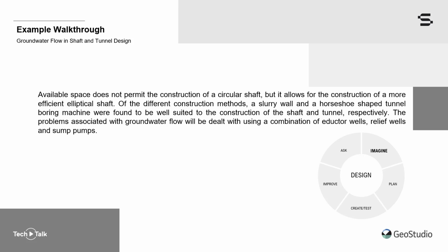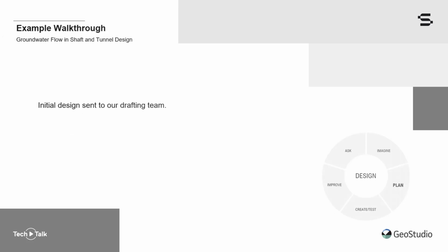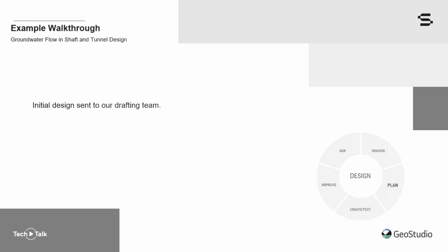The problems associated with groundwater flow, such as inflow, boiling, and heaving, will be dealt with using a combination of eductor wells, which use the Venturi principle, passive relief wells, and sub-pumps. After sketching several ideas, we've sent an initial design to our drafting team.